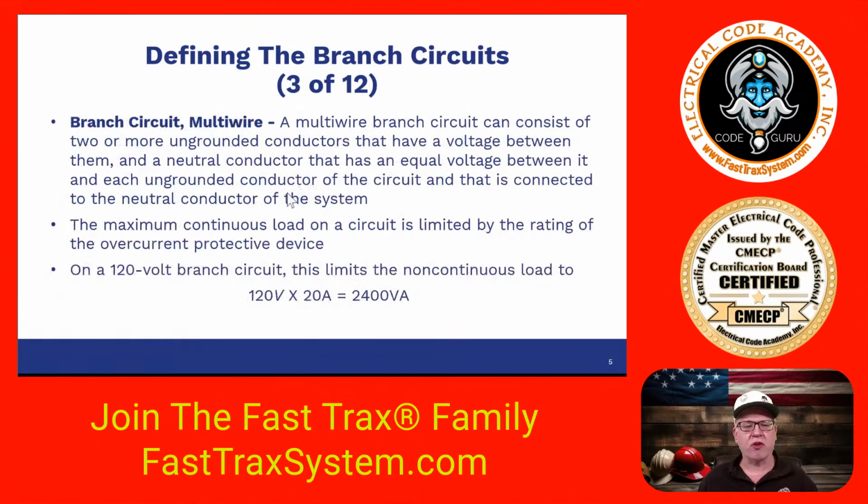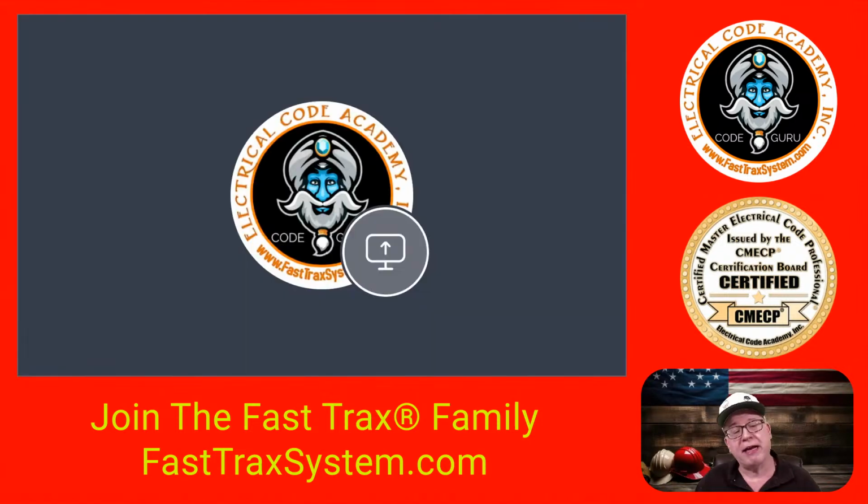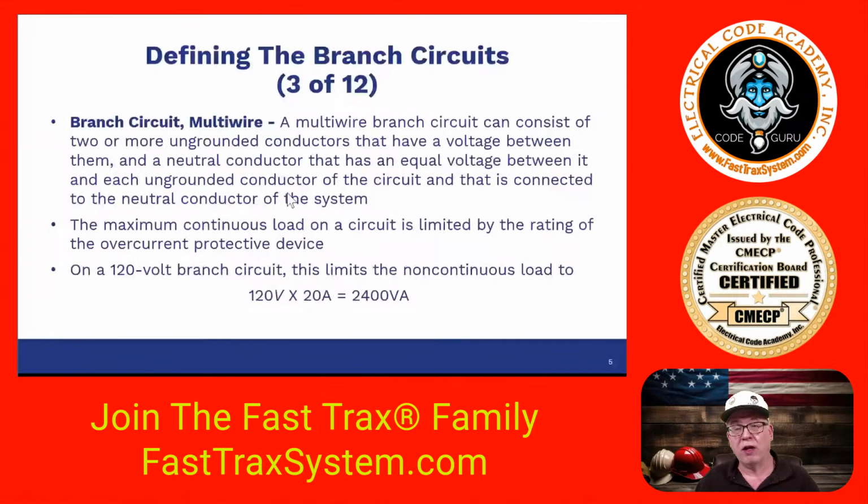Now, that also brings us to a concept of what's called multi-wire branch circuits. And there are people out there that literally don't like multi-wire branch circuits. But what are they? Well, in layman's terms, it's two hots that are sharing a neutral, so that if there's 10 amps on one, a red, let's say, and there's 8 amps on the black conductor, and they're sharing a neutral, then only 2 amps will be present on the neutral.